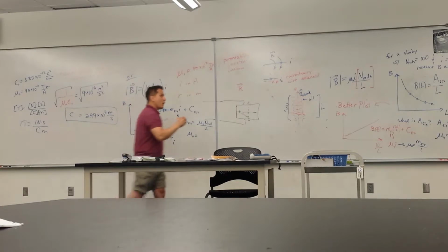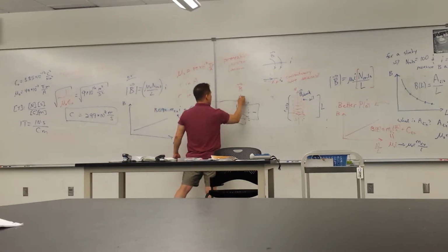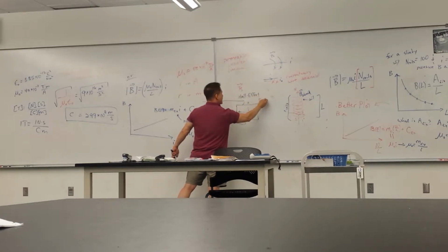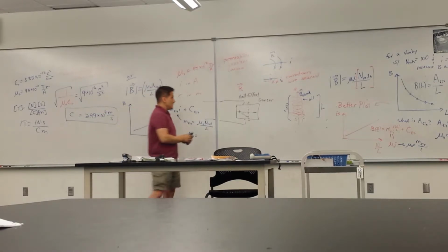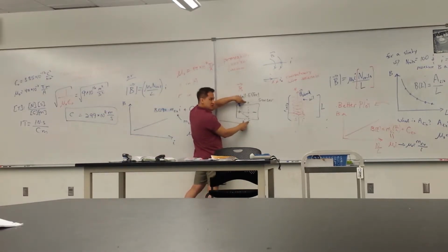So this is called a Hall sensor, or a Hall effect sensor. And this is what our magnetic field sensors are. It's the only way we can measure actual magnitudes of magnetic field, because this induced voltage, lateral voltage, if you will, Hall potential, we sometimes call it, is directly proportional to the field that's bending.